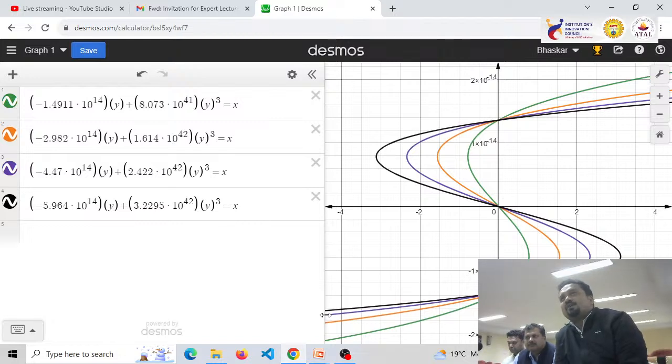So this was about the charge versus voltage characteristic for isolated ferroelectric capacitor, which I have obtained by solving the LK equation, which is known as Landau-Khalatnikov equation. And you can see the signatures of negative capacitance in these graphs. Similarly, like what we did for charge versus voltage, we are going to study U versus Q, energy versus charge.